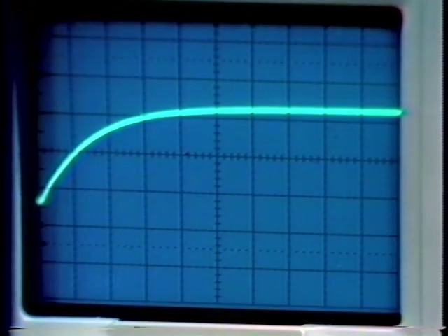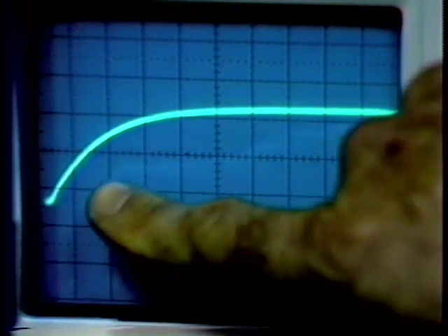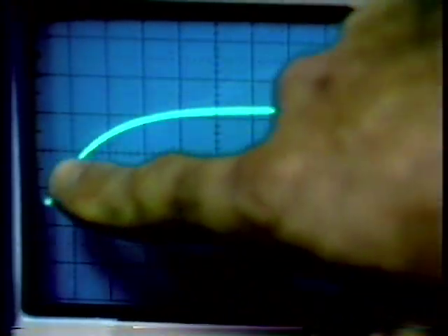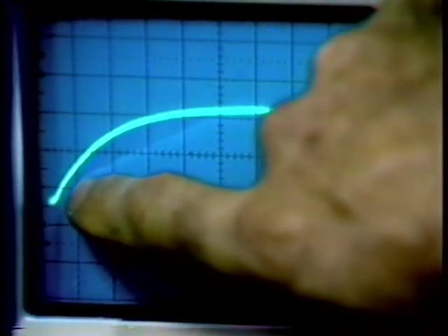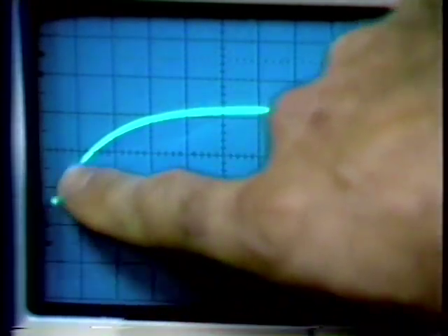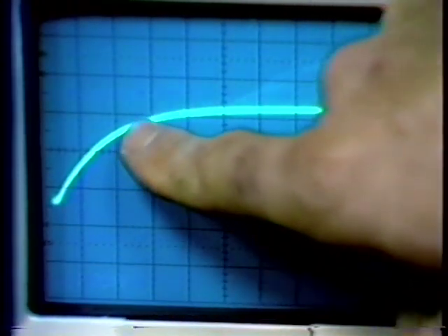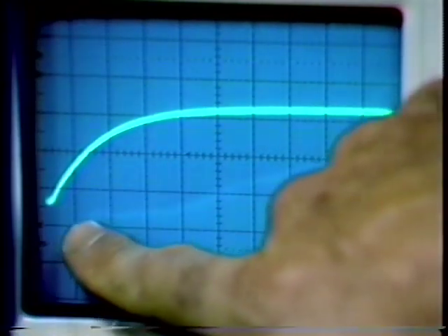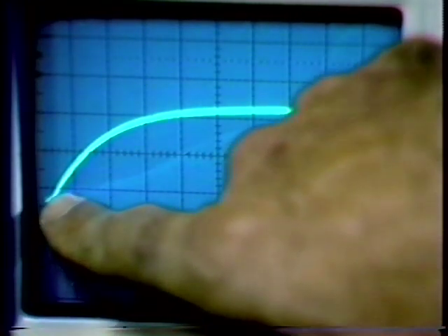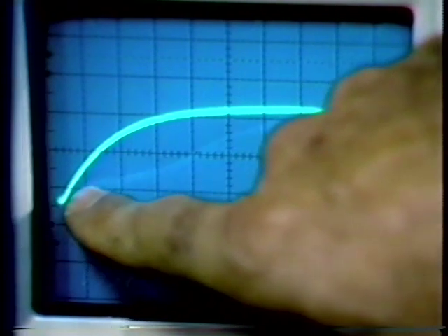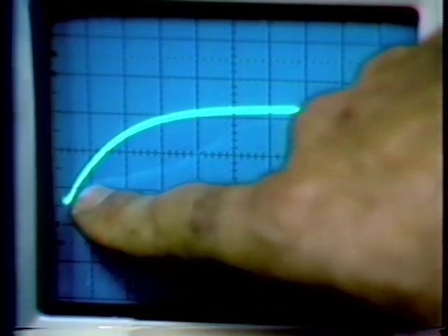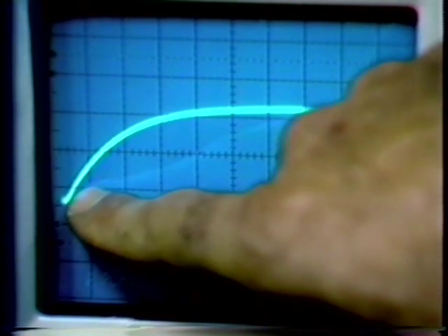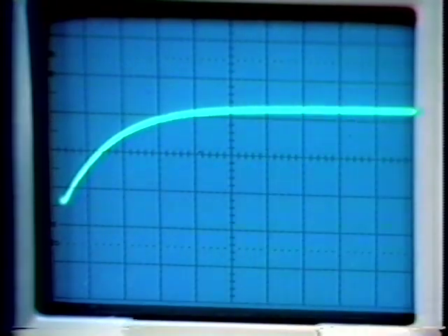And we notice, to a very good degree of approximation, a first-order kind of step response. Here we see something that looks very much like a simple exponential. We can calculate the effective time constant of that exponential if we cared to. And the only possible difference comes right at the very, very beginning. There's a little departure from pure exponential behavior right down at t equals 0 for the step response of our amplifier.